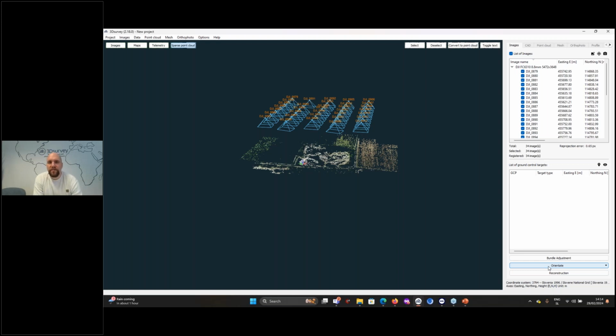Even if we have an RTK drone, that drone will have GPS on board, but if we want 2 centimeter accurate elevations, so let's say 2 to 4, what surveyors need, we will still need between 1 and 4 ground control points per flight. If we have a drone that does not have RTK GPS, then we recommend you place between 6 and 9 ground control points per flight.